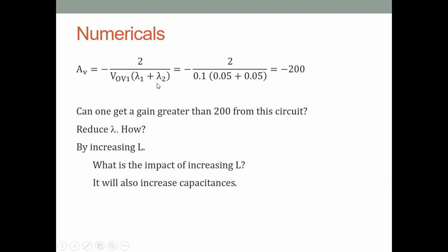Again, because the sizes are smaller, the power dissipation or the power consumption is less, because the power goes as half C VDD squared, where C is the capacitance, and because the capacitance is reduced, the power is reduced. So shrinking in technology has been just a blessing and wonderful for digital circuits, not true for analog circuits.